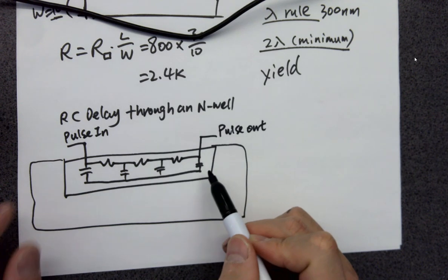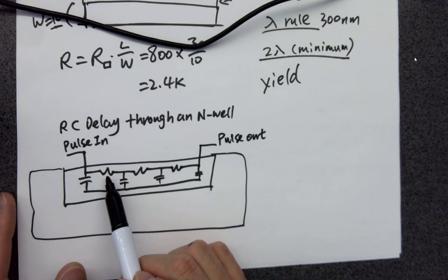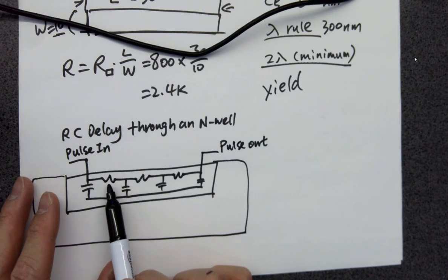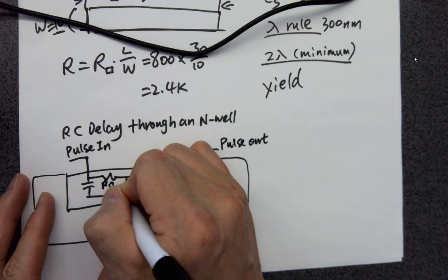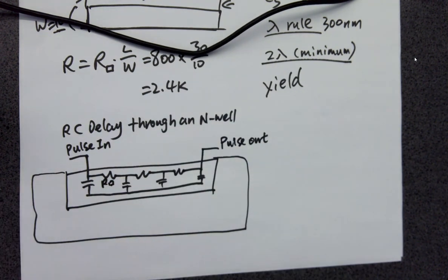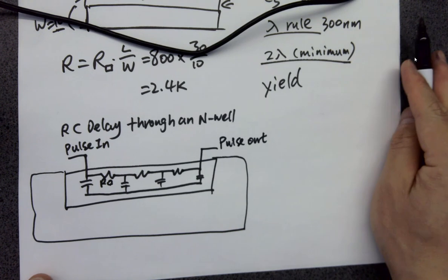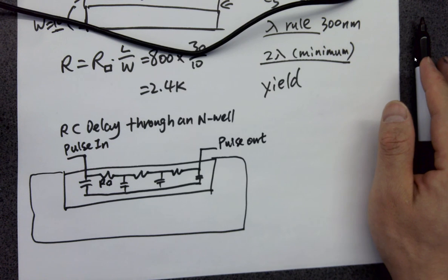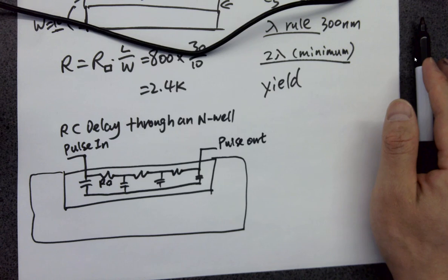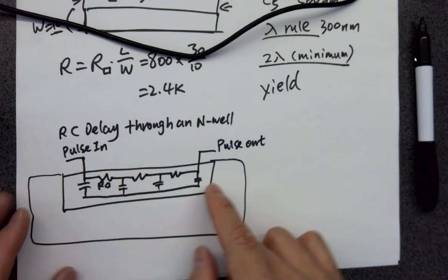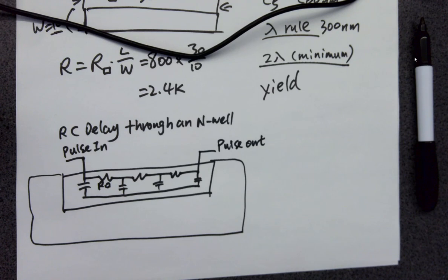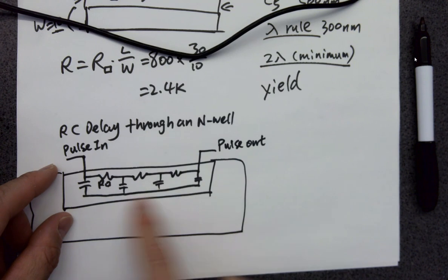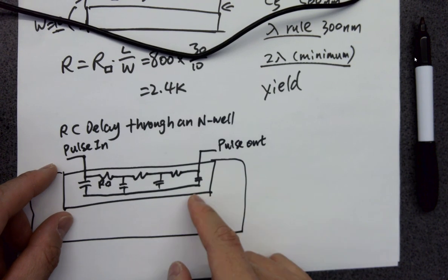So what is the capacitance I'm modeling here? The resistor you can understand because it's a piece of N-well and we divide it into its sheet resistance. So that's R square. So what is the capacitance over here? Why do we model a capacitor for the N-well? The reason is that it has parasitic capacitors as an N-well. So whenever you are driving the N-well, it's not just a pure resistor causing time delays. That's why we model it.